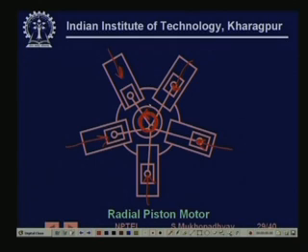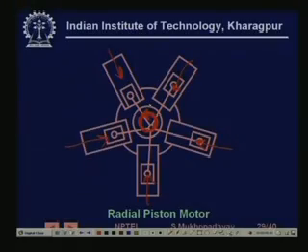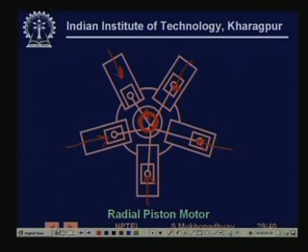Naturally this is of a positive displacement type, that is, in every cycle of the piston movement a certain amount of air goes through the system. Similarly, you can have non-positive displacement type. Here we have not shown a figure, but it is exactly similar in principle to the vane motor of hydraulic systems, although there may be constructional differences in design.